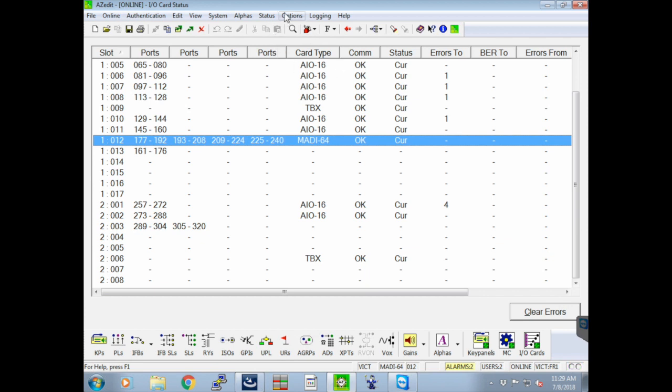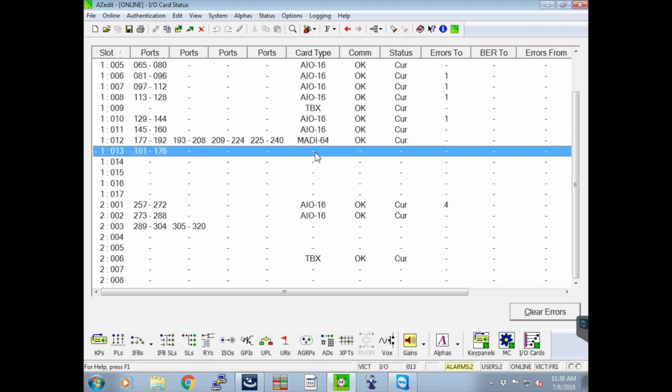So if we wanted to add a card to a frame, say for example we wanted to add an RVON card on this show, a couple steps we need to take care of. First, we want to figure out which slot we want to allocate it to. Then you need to physically go to the frame, install the backplane first, and then once we have determined that the backplane is in place, we can go ahead and slide the front card in to the backplane in the slot that we've chosen. When you've done that, the intercom system will report that there's a card in that slot,